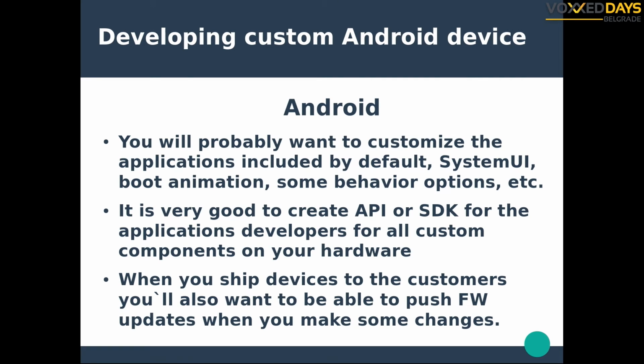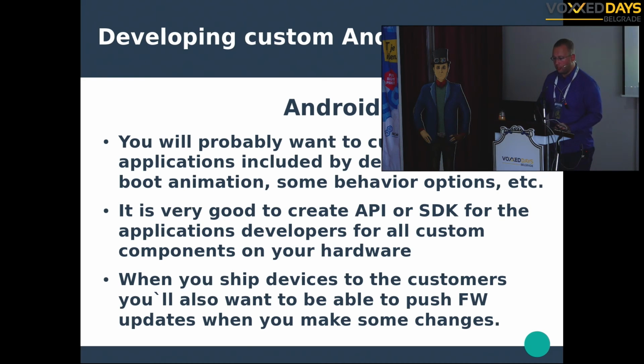That's why I'm mentioning it, because developers were opening the file which was controlling the LED and turning it off and on, and then we sometimes had situations where several things wanted to flash the diode, and it looked bad. But this is the way you solve it: make some higher layer, some service that will be the only one that controls the hardware, and the developers will talk to the service. So this is another point that you should think about when creating your own hardware.